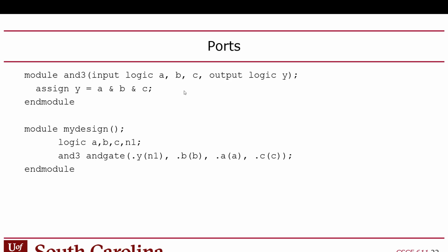But even when you simulate it, there's a consequence of this. There's a nasty side effect of having these modules. The side effect is that the same signal, the same physical wire, has different names depending on what module you're looking at it in, what the context, what the scope is.